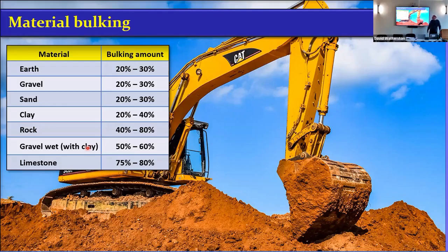Great. So you phone up a haulage company. So you get 10 meters of material to come out. How much are you going to charge me? £500 a truckload. All right, fine. When they take it out, the truck only takes 10 tons, say, right? Which is 10 cubic meters. But you've got another 60%, so you nearly get 1.5. They need 1.5 trucks. So you got a second truck in, which is another 500 quid. And you didn't expect it. So bulking can have an effect on your material taken away.